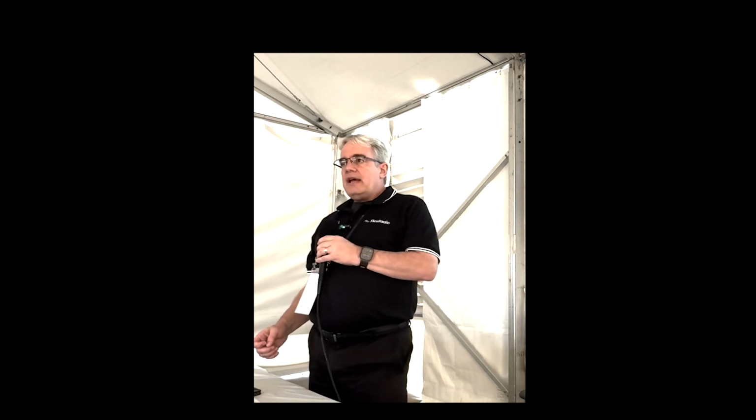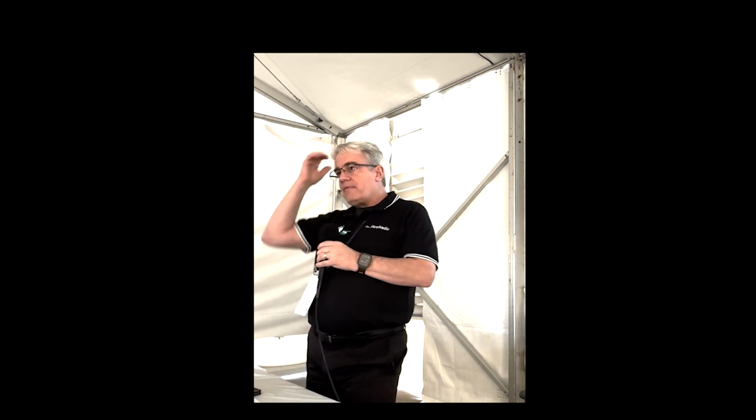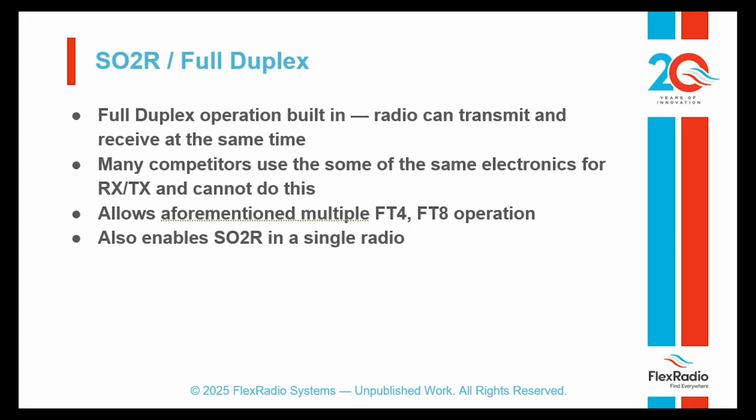We also have SO2R and full duplex capabilities inside the radio. Why do you care about that? So SO2R allows you to run one operator with two different radios. The typical mode of operation is you'll call CQ on one radio and you'll go over and work somebody who's answered your CQ on the next radio while somebody's calling you over here, and then you toggle back and forth.